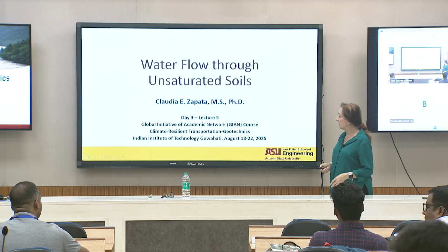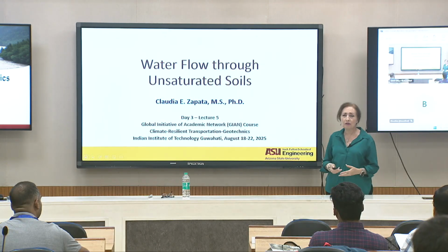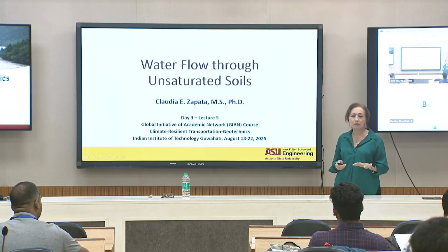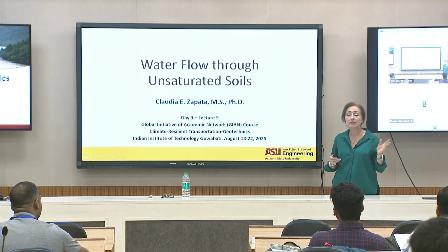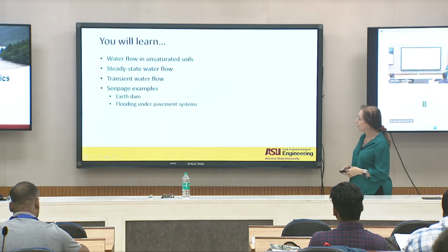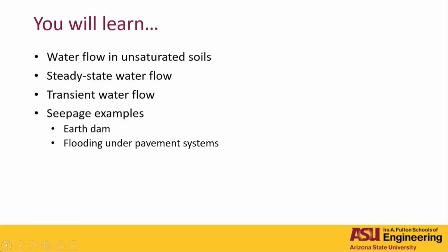Today we're going to see the water flow through unsaturated soil. I'm going to get a little bit more into the steady state and transient conditions. And I have for you a couple of examples that we ran in Fluxes for you to understand how all these theories apply to practice. So you're going to be learning about water flow, steady state and transient water flow. I briefly touched on that yesterday.